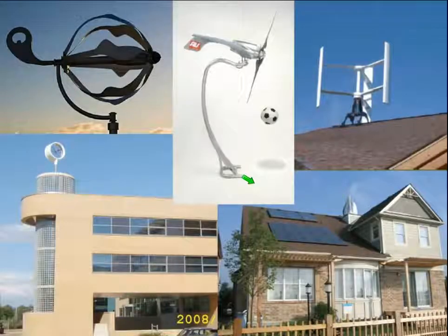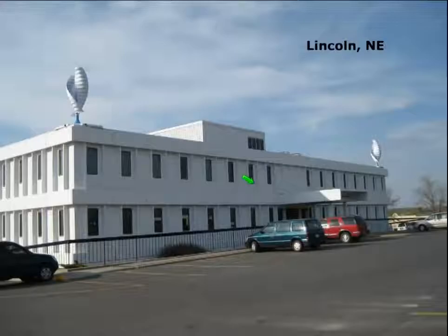Okay, here's what I know everybody's excited about. People are excited about small wind turbines and putting them on buildings. And I am absolutely not excited about small wind turbines on buildings because of the 2 reasons I already showed: there are low wind speeds, so you don't produce much power low off the ground, and number 2, you have turbulent winds, which are slower and, again, not producing much power. So let's just give some examples.